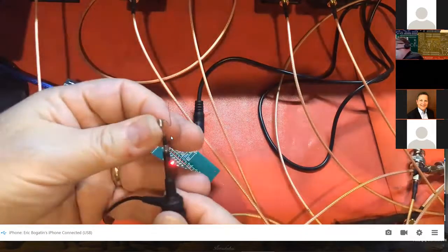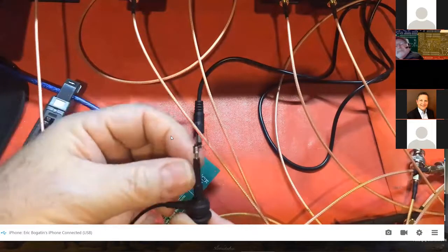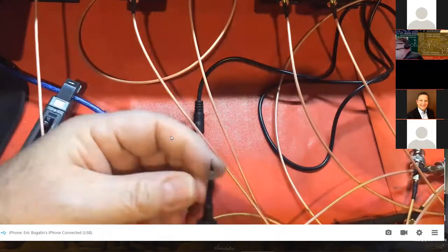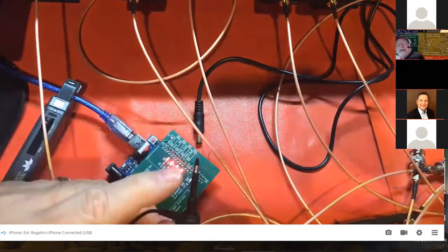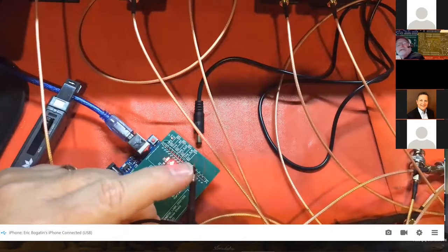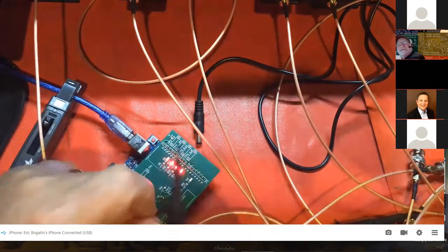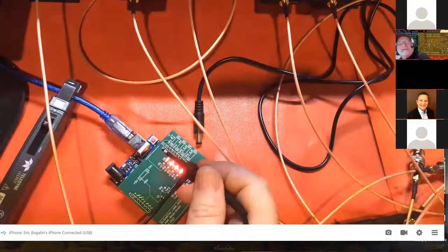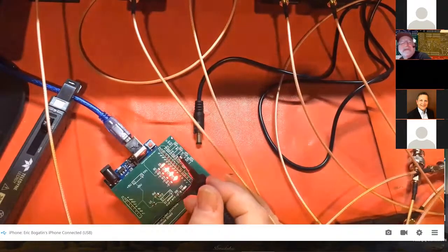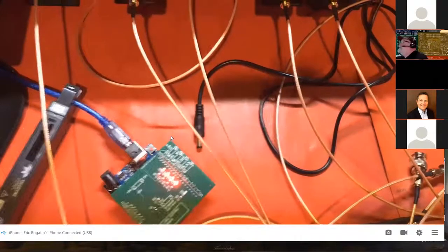Because when we take that little spring, it's just a little steel spring making contact there, we screw it on there, it wraps itself on there, makes a tight connection, and now we have a really small loop between the signal and the return, and that's what makes contact between the signal and return on the board. And if you notice on this test board here, conveniently, I have test points that have, let me see if I can zoom in on that.